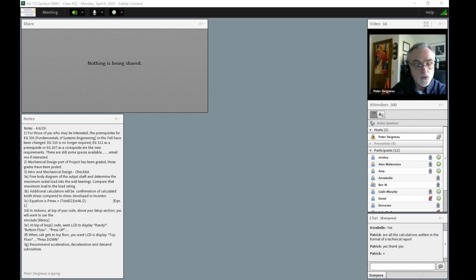So in your code, there will be what I will call, this may not be the exact variable name that we will end up using, but I just want to give you an idea, a PWM max value, which will be the highest speed that will allow the system to be run at. And then there will be something like a PWM min. And then there'll be an intermediate value, which is like a cruise speed value. You can call it anything. I forget what the variable name was in the previous code, but again, I'll specify that on Thursday.